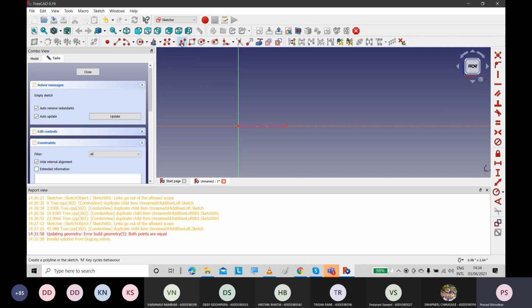So go to polyline, select this one, and see now this constraint appears. So make sure you select the appropriate constraint, or you adjust the mouse so the constraint is proper. Okay, and then click on the M button on your keyboard, and that toggles the type of section that is editing. Okay, so this is quarter circle.